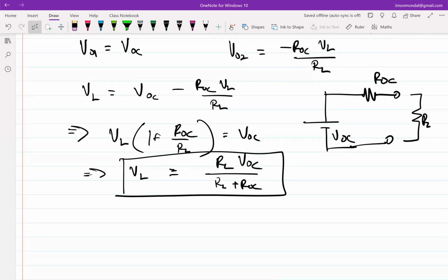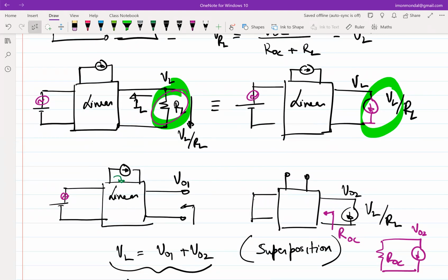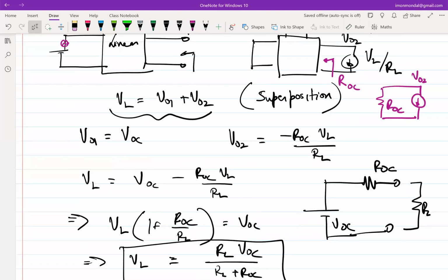Okay. So any questions regarding these steps? Okay. Fine. So as long as you are satisfied, I'll not prove Norton's theorem. Norton's equivalent is what? You can just tell me the statement. Right. So essentially, instead of the open circuit voltage, I will replace it with a short circuit current source. How do I experimentally find it? I short the output and figure out what is the current flowing through it. We call it the short circuit current. And the open circuit resistance, anyways, we know.